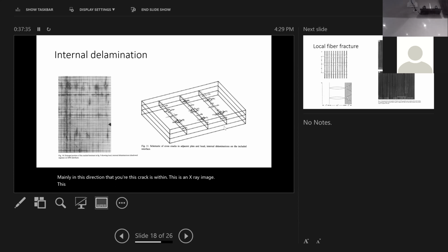These examinations are done by fatiguing the sample, then you introduce a penetrant. It's usually a liquid with heavy elements, like iodide, which produce a heavy X-ray shadow. You infiltrate the material with those compounds, and then you look under X-ray and you see the shadow. The shadow is where those element penetrants are entrapped. So you see the shadows here.